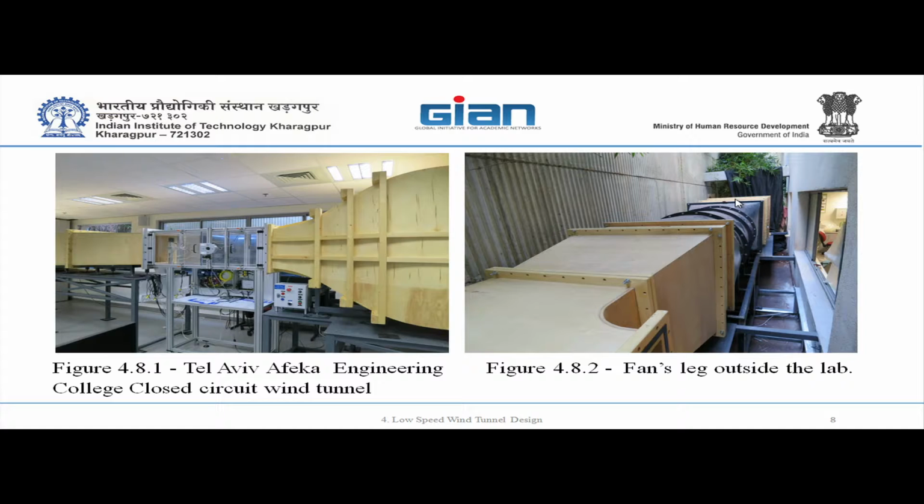Every corner will contain turning vanes. We don't let the flow just turn freely, because then it will build up a velocity gradient according to centrifugal movement. So we have to break the bulk flow with vanes in the corner. So all corners will have turning vanes.